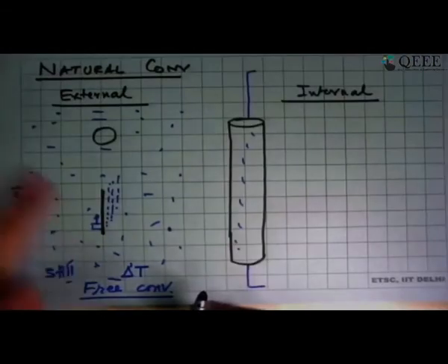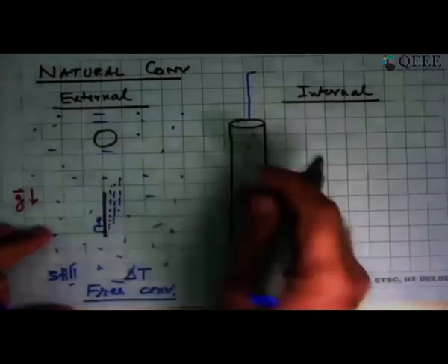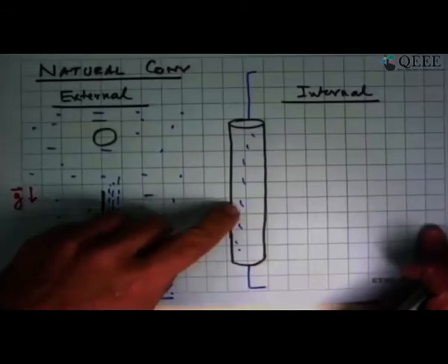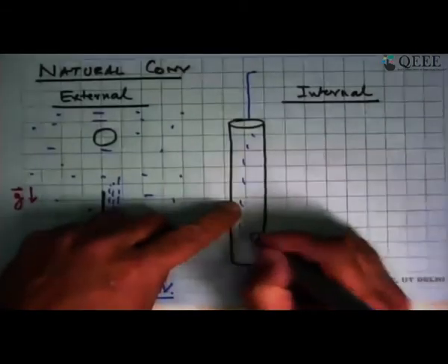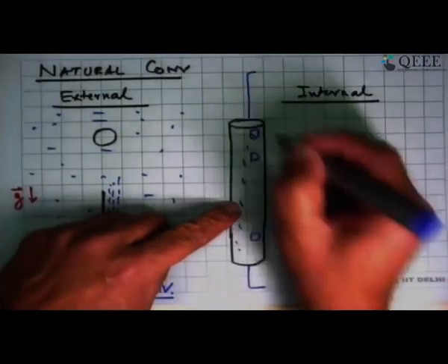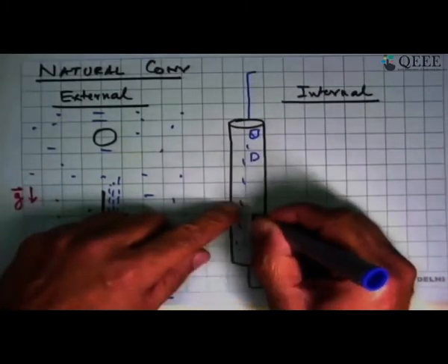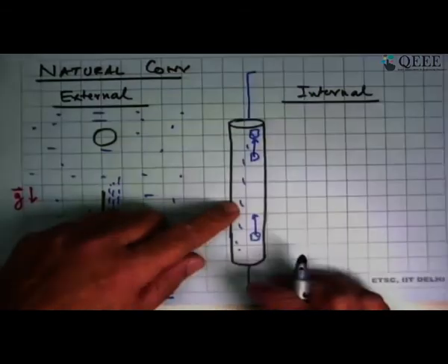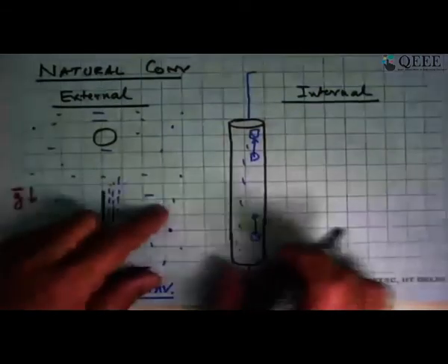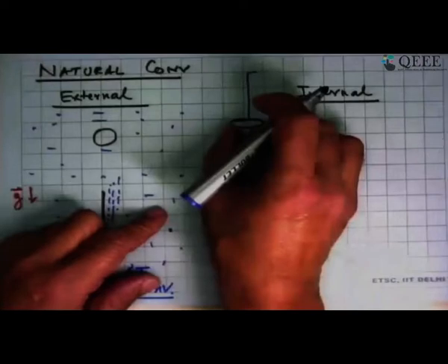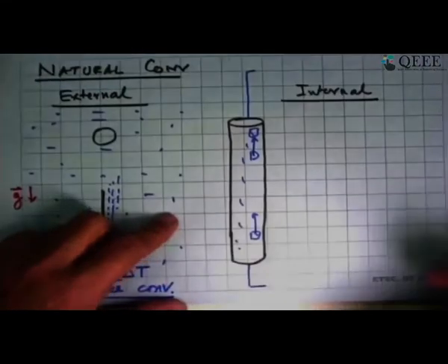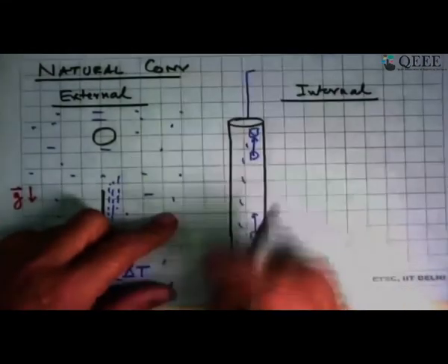And what we rely on is that as this tube surface gets hot, the fluid gets hot, and because of temperature gradients within the fluid, this fluid is set in motion. So there is no external thing here, but temperature gradients within the domain is what's causing this flow to take place. This is an example of natural circulation in internal flow.